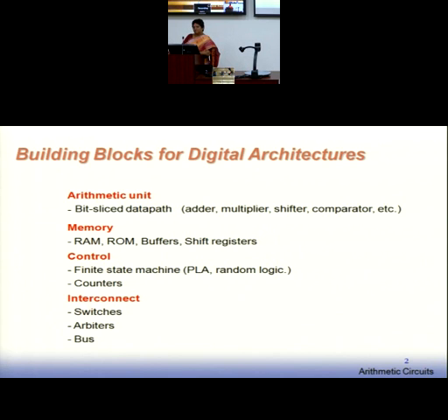And in that you will see two major blocks which are very, very frequently used. That is an adder and a multiplier. A subtractor is a modified form of adder. And similarly, if you have developed an adder and multiplier, a divider is also kind of a subtractor, a repetitive subtractor. Okay, so if I know the fundamentals of adders and multiplier architecture and its impact on performance, I can very well extend the same principles to subtractor and divider.